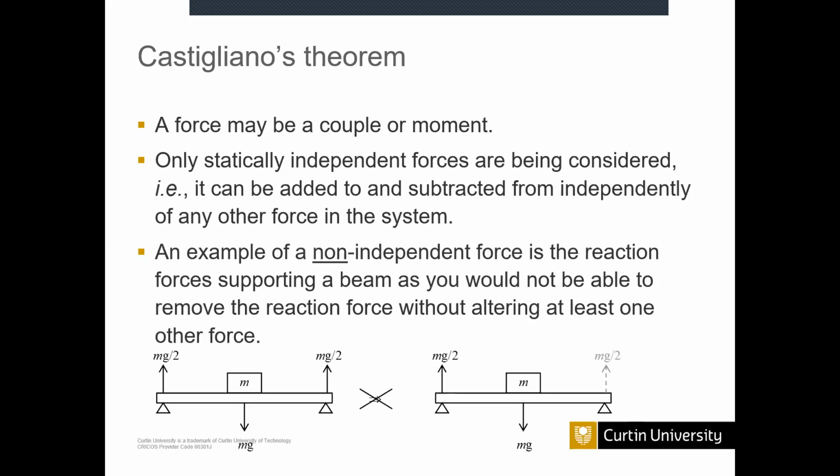For non-independent forces, you can't use this theory. An example of a non-independent force is the reaction force supporting a beam, as you would not be able to remove the reaction force without altering at least one other force. You can see, due to the weight on this beam, at the supported point there is a reaction.